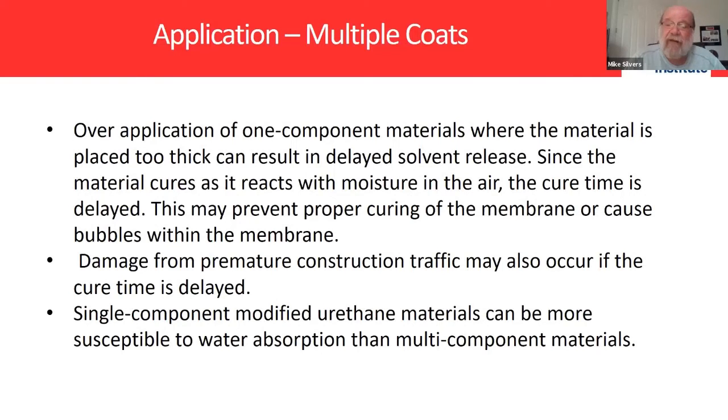We did a lot of asphalt over concrete, and Glenn will know this. We had a real easy way to check and see if concrete was too wet or not. You took a little hot asphalt and poured it on the concrete deck, and you let it set up. As soon as it got hard, if you could peel it off the concrete easily or at all, it was too wet.